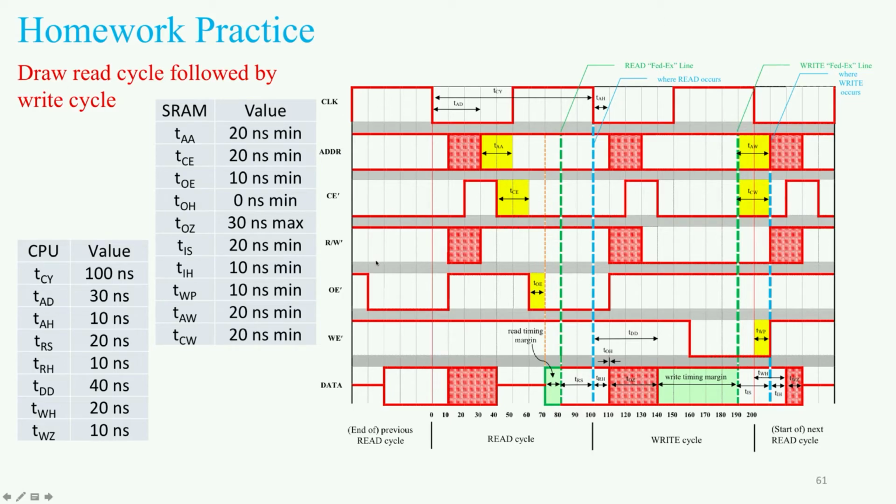Now let's look at the read-write bit. The read-write bit has the same characteristics as the address line in these simple address-data bus systems. It's held constant from the previous cycle for this long. It's flipping around for 20 nanoseconds, and then it's going to be valid in the state that it needs to be for a read, and it needs to be a 1 for a read because that's how the bit works. Then it becomes valid. So this read-write line effectively follows this address line perfectly, because they're both reflecting what's happening inside of the CPU.